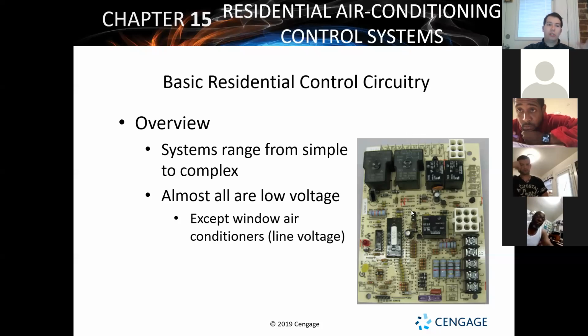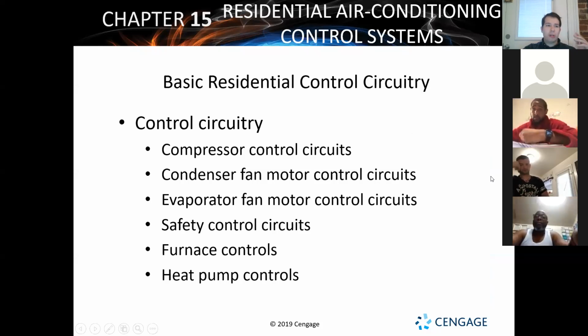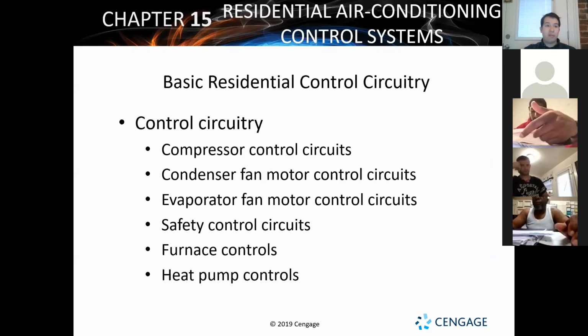Is it sending that voltage? Otherwise, bad board. But it's just a matter of understanding how to read those. Different manufacturers and different wiring diagrams will explain what's connected to what, and from that you can figure out when you should be reading 24 volts here, or 240 here, or 120, wherever.